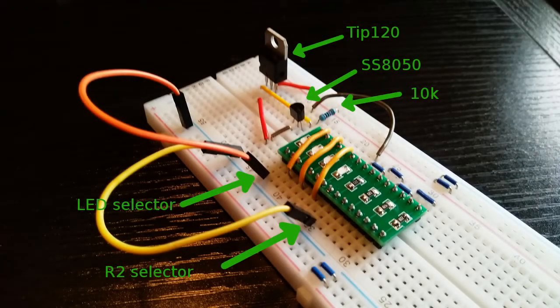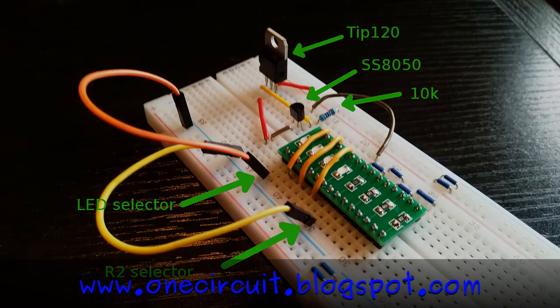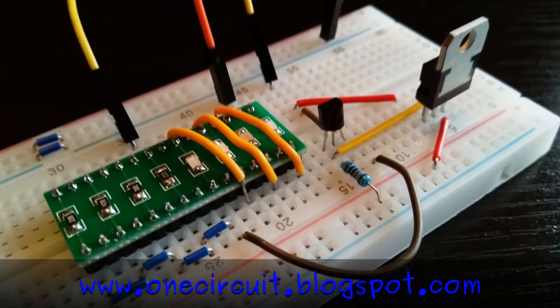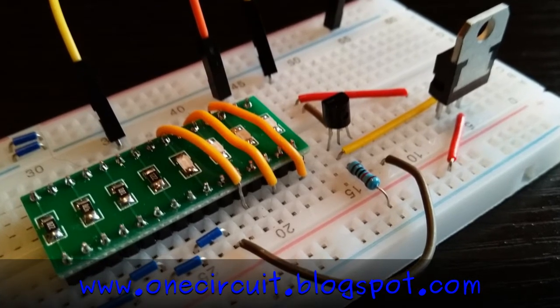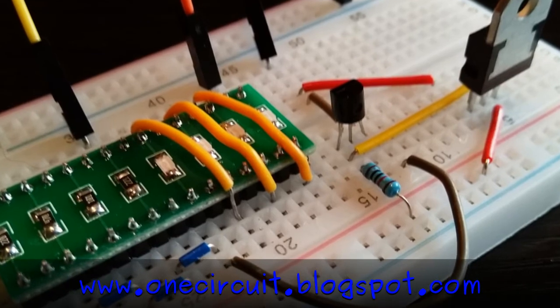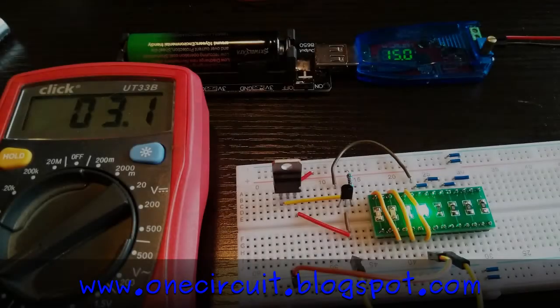Okay, so here's the setup where we have a Darlington transistor and a normal BJT, an SS8050, and I've set it up with the 1206 adapter there. I've got 4 different resistors that I can select from and different amounts of LEDs that I can select from as well. So this is the first constant current circuit, and here it is working with just 1 LED.